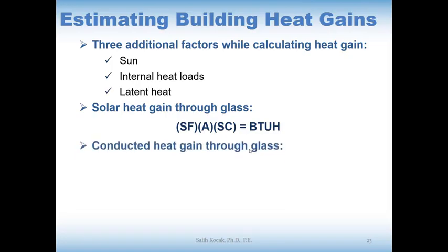And there will be another heat gain. This is going to be the conducted heat gain through the glass. What is the conducted heat gain? Again, it is nothing but U times A times the temperature difference.